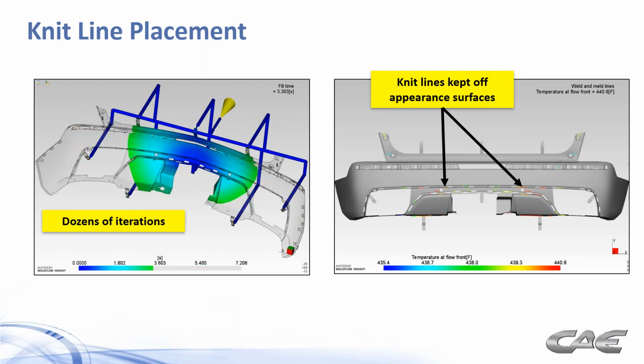Got another question on the questions tab here. It says, is a 0.6 second injection time feasible for a 500 millimeter length flat part of 1.6 millimeter thickness when the molding window is giving the same injection time range of 0.45 to 0.6 for Vectra A130?